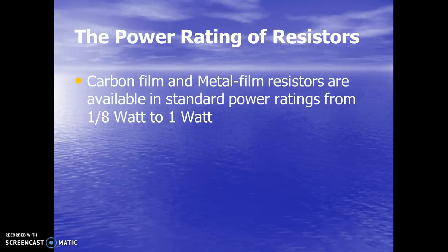And the wattage values are typically very, very low. If you want to, you could do a quick calculation, and who knows, I might put that on a test, a calculation about what kind of current a resistor can handle based on its power rating. Or I might say how much voltage it could handle, and you'd have to calculate the maximum wattage it could handle and go from there.